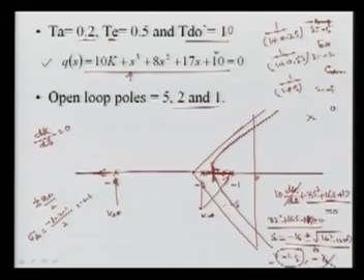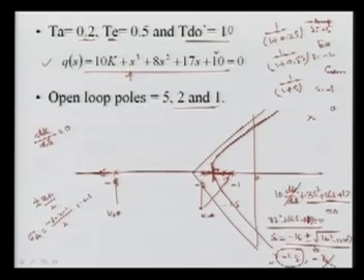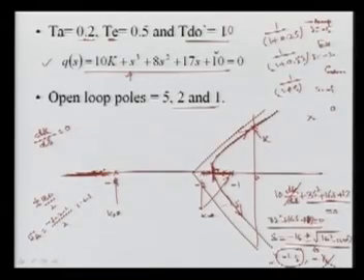By changing K, the characteristic roots will be moving with the movement of K. So if K from 0 is increased, the closed loop poles move in this direction, and the other 2 roots go in this one. Now you can see that once we increase it, this crosses your imaginary axis, and once it has crossed, your system will be unstable. So the gain, the critical gain, must always be less than this, otherwise it will be unstable, unless you go for some compensation techniques.